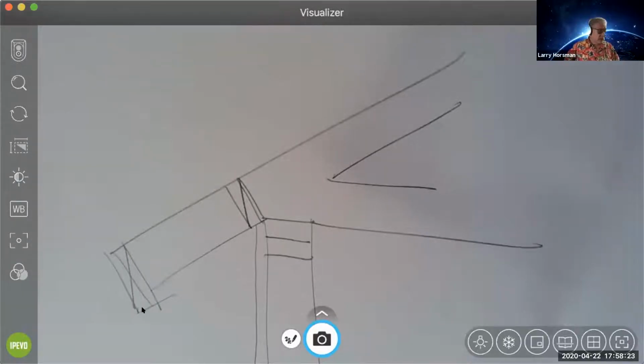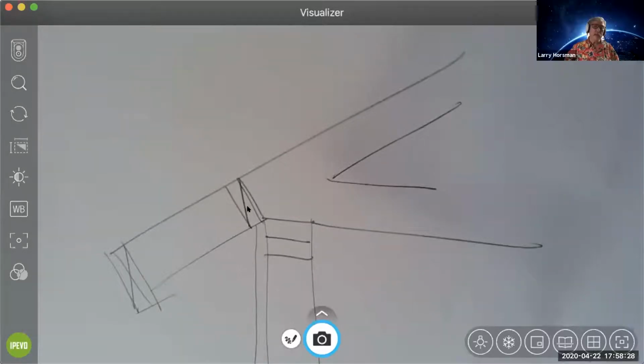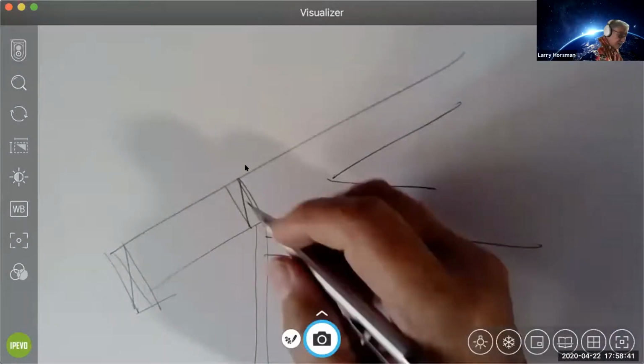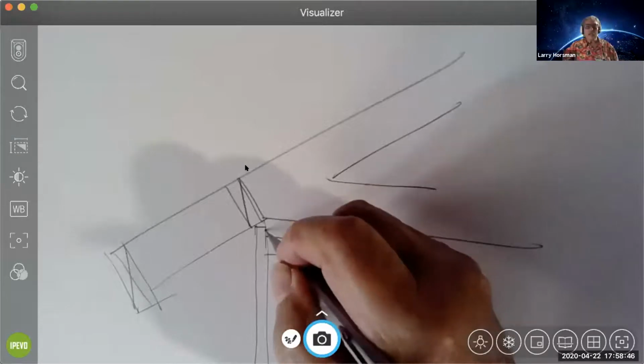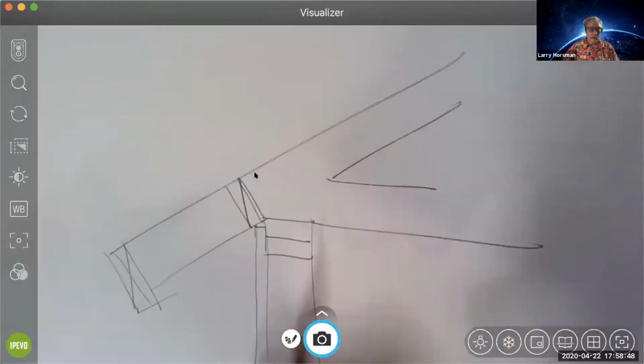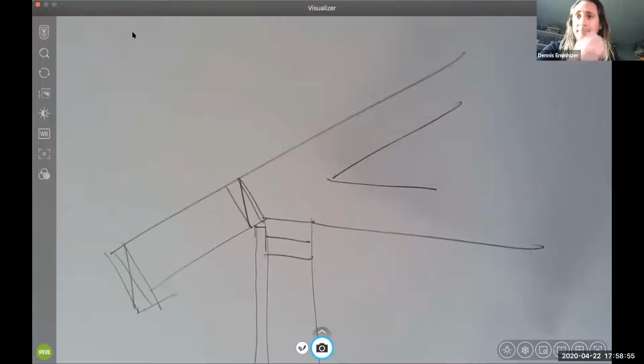So this is the standard detail. They used to just put the blocking out perpendicular. It sticks out 1.5 inches. The stucco's only 3/4, and they just butt it up there. There's also, you can buy a piece of sheet metal, a stucco stop, that looks like that. So it's like a reglet. I don't know if you can see that. Let me blow that up. I can see it fine.